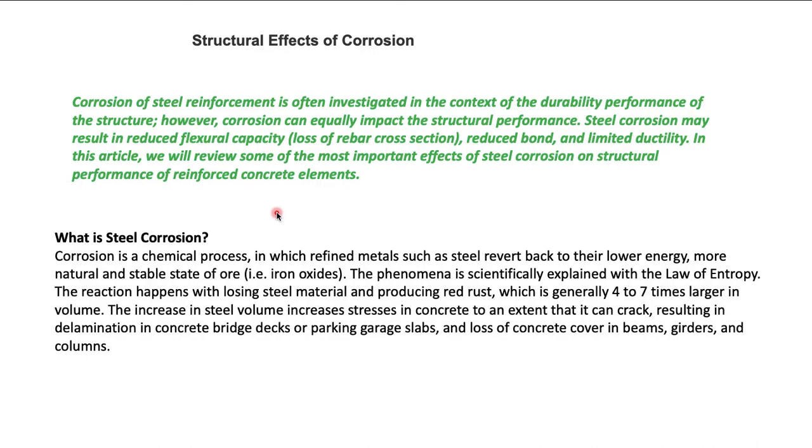The structural effect of corrosion is also a main factor here. Corrosion of steel is often investigated in the context of the durability performance of the structure. However, corrosion has an equal impact on structural performance. Steel corrosion may result in reduced flexure capacity, simply put, loss of removable cross section, reduced bond, and limited ductility.